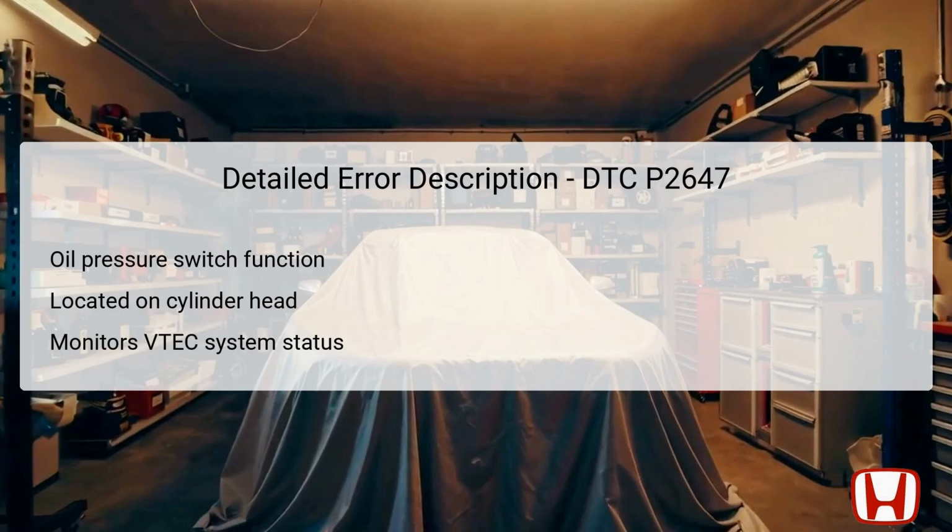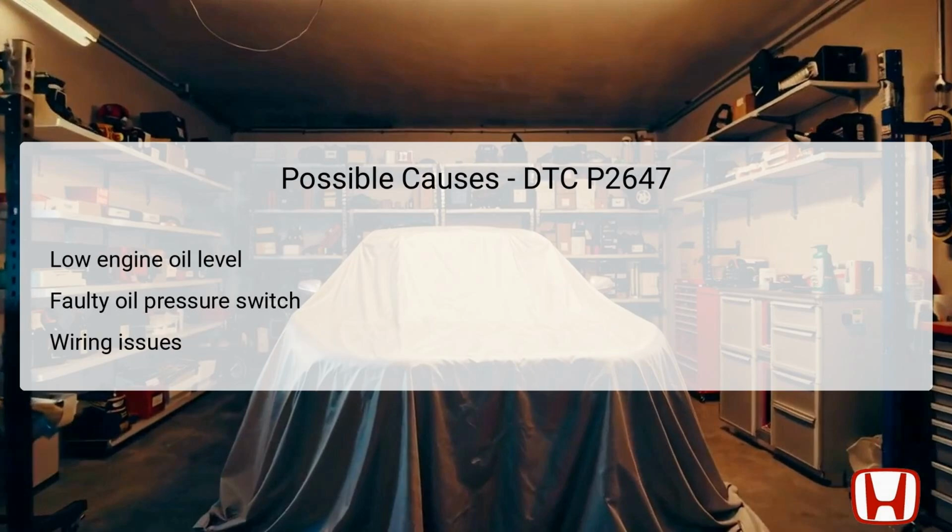A high voltage reading in this circuit suggests an electrical malfunction that could potentially disrupt communication between the switch and the PCM. If the PCM does not receive the correct signals, it cannot make necessary adjustments to the VTEC system, which may lead to performance issues. Verifying the proper operation of this switch is vital in ensuring a smooth-running engine, as it directly impacts power delivery and fuel economy. Several potential causes could lead to the triggering of DTC P2647.